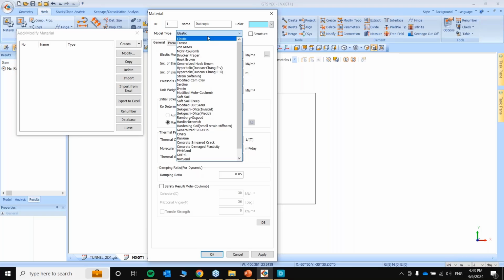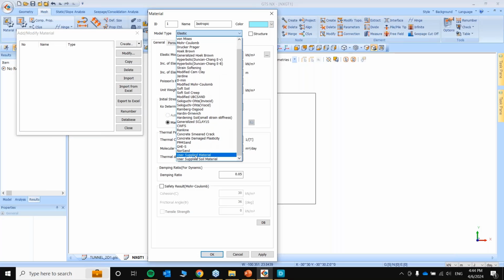In terms of material database, we have a huge database. So you can use literally any kind of soil or rock model you want, provided it comes under the FEM theory. So we have Mohr-Coulomb, Hoek-Brown, then strain softening, or we have CWFS, that is the cohesion weakening friction strengthening rock, or else we also have the generalized Hoek-Brown, or you can have your own material properties too, where you just apply the material model in Fortran.